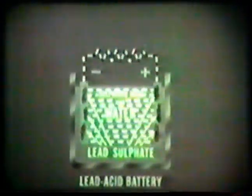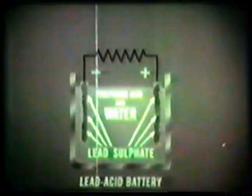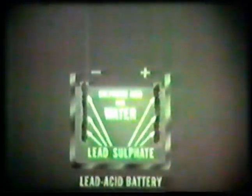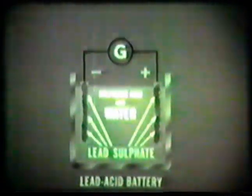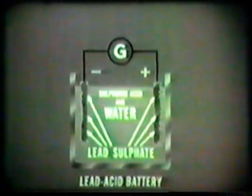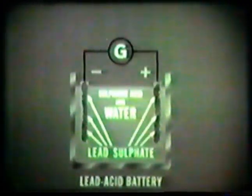As the electrolyte becomes weaker and the sulfating increases, the battery gradually loses its charge and finally is fully discharged. The chemical reaction is spent and the electron flow ceases. Current can again be drawn from the battery only by charging it. Charging is accomplished by connecting the poles of the battery to a generator or battery charger. In the aircraft, while in flight, the aircraft's generator keeps the battery at full charge. During servicing, an auxiliary power unit or a battery charger may have to be used to recharge a battery.